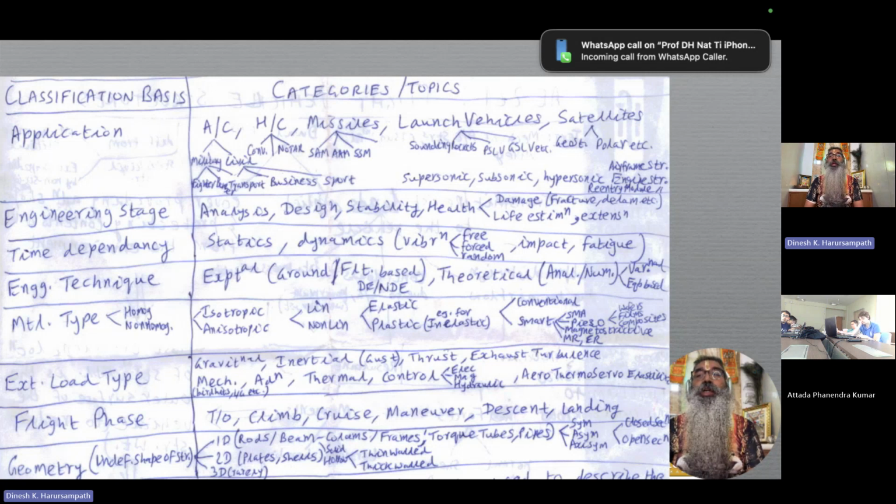And it becomes even more critical when there is an ingestion of a bird into the engine, and it hits the rotor blades of either the fan or the compressor or the propeller. Then you will have a severe issue unless and until the design takes care of it. And the design does take care of it, because the certifying agencies have very critical requirements related to that.